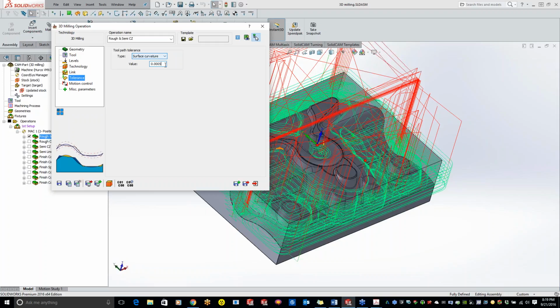Now, we already set up the tolerance of the model when we set up our target, but this is another spot where you can set it up so you get much smoother results. The larger I make this, the more straight line moves we will get, and the smaller the value we put in there, the smoother the lines we'll get. Usually with the default, you can basically skip this page and just get to link and skip the rest of it, but we'll definitely go through it.